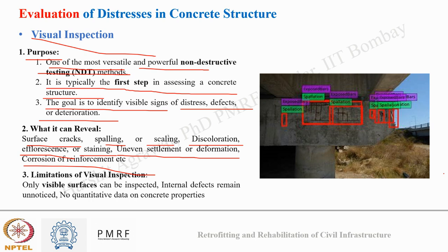So we can see in the image how just from the image we can identify distress and the cause of that distress. You can see here exposed rebar at different locations and spalling of concrete. So we can comment that this was due to corrosion of embedded reinforcement. Now based on the exposure condition, if it is near the seashore, we will say corrosion was due to chloride attack, and if it is away from the shoreline, it may be due to carbonation of concrete. So ahead we can assess the carbonation depth of the concrete also and give a strong justification for the defect.